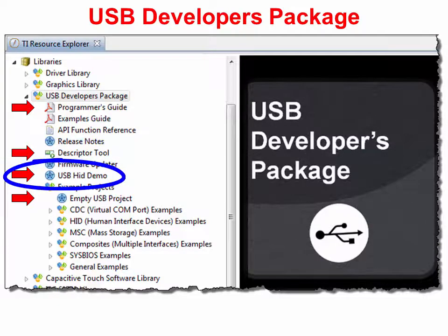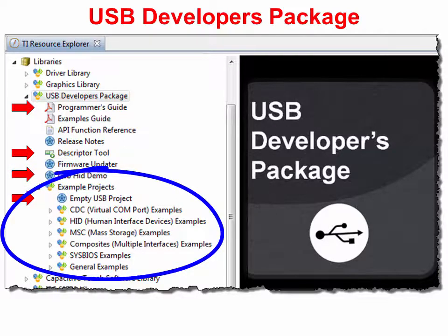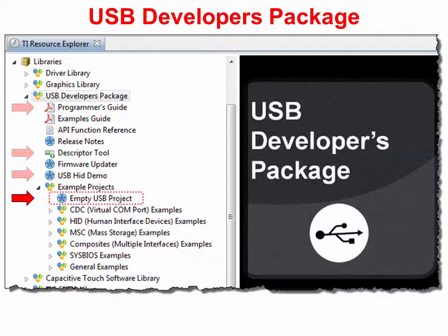The USB HID demo is a host-side tool that lets you interact with custom devices implementing the Human Interface Device class. It's like a serial terminal program for HID devices. Finally, the rich set of examples provided by TI not only give you a way to play with USB, they also make excellent starting points for your own applications. We recommend that most users start out with either one of the many examples provided with the developer's package or the empty USB project example. Let's take a quick peek at the empty project.